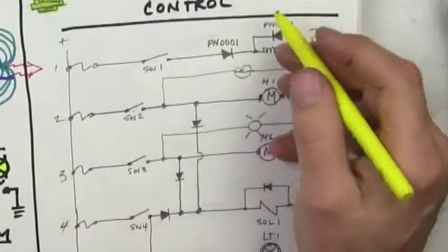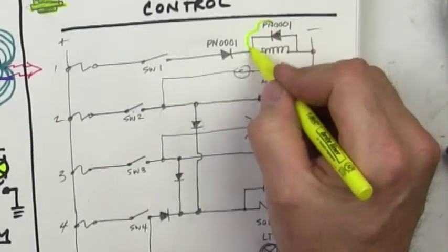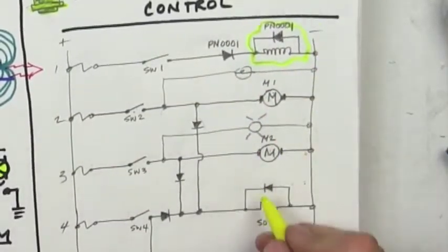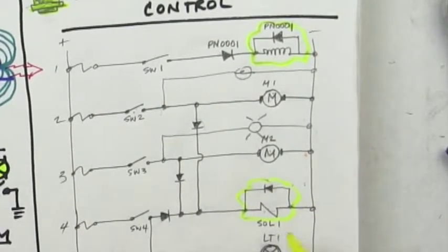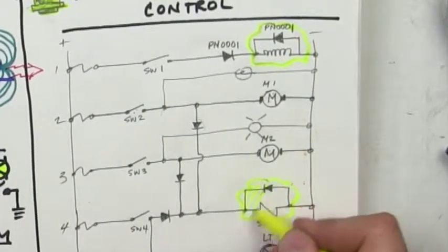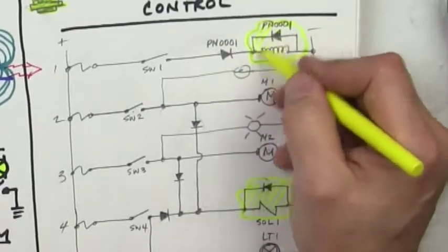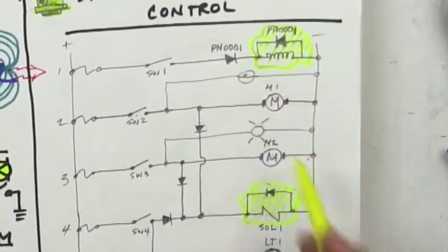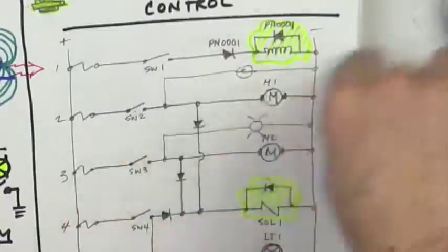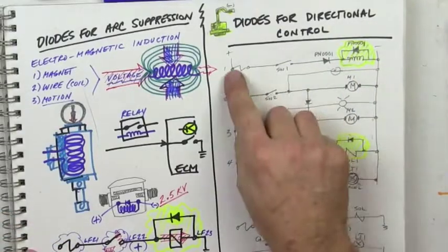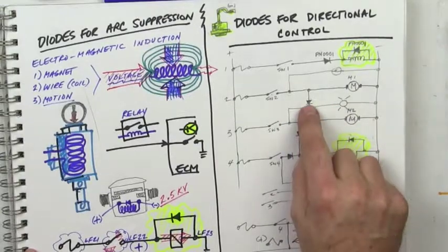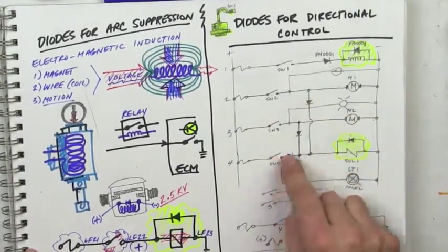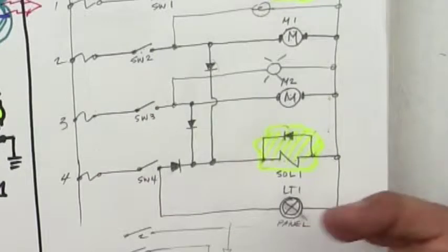So, quick reminder that I treat a suppressed solenoid or relay or clutch, whatever, as one thing, and that makes it simpler because you don't have to worry about current flow. When I'm looking at diodes in circuits, what matters to me is whether the diode is pointing towards ground or towards positive when the circuit's turned on.